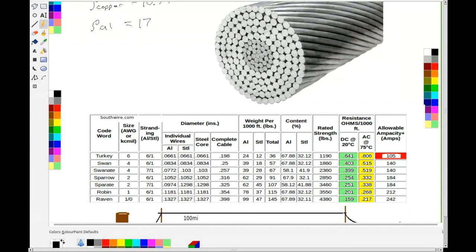So with the American wire gauge sizing, the smaller the number, the bigger the wire is. Okay. And the other thing that you notice over here, though, is you'll notice at DC, okay, DC resistance is smaller than AC resistance. And part of the reason for that is there's something called the skin effect. I think we've mentioned it earlier in the semester.